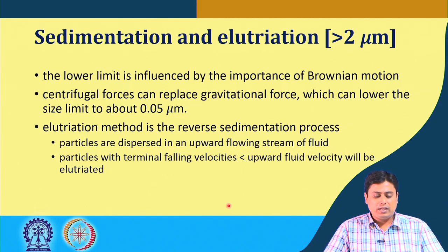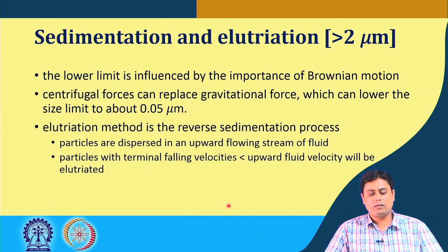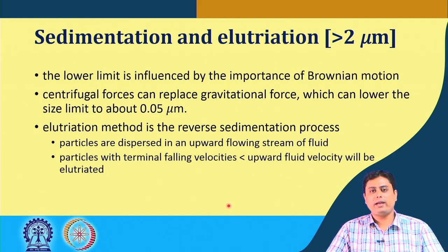The lower limit in this case is influenced by the importance of Brownian motion, because as we decrease the particle size, Brownian motion becomes dominant. So, we have to set the lower limit accordingly, or we can determine it based on the fluid property that we choose when these particles are sedimenting.